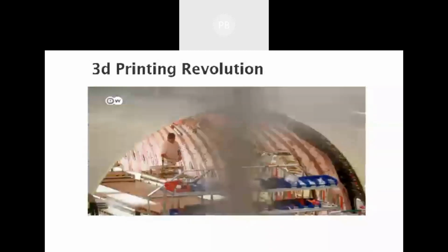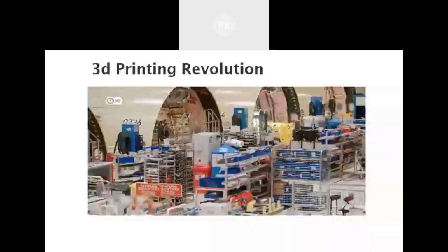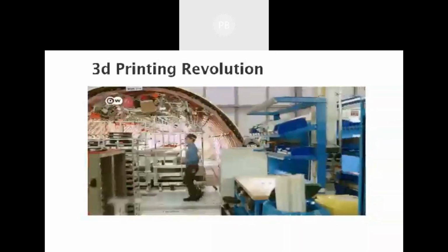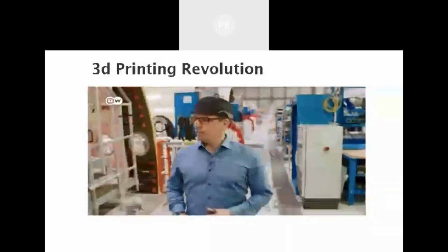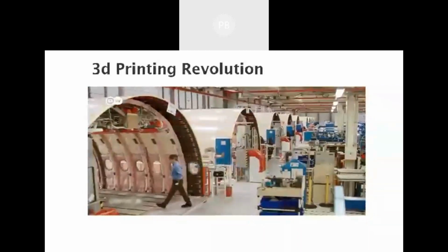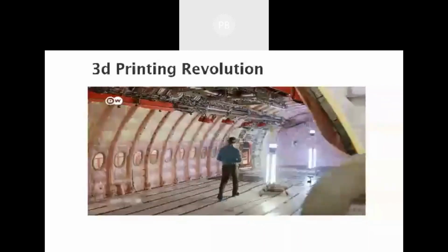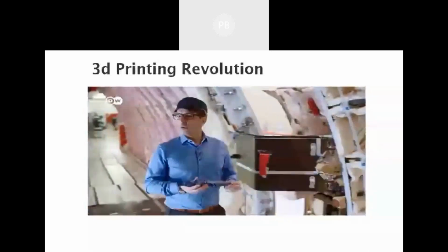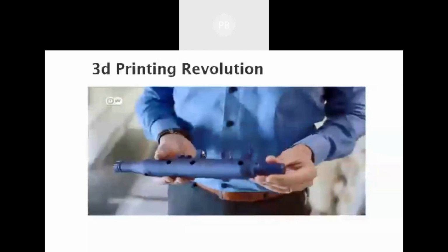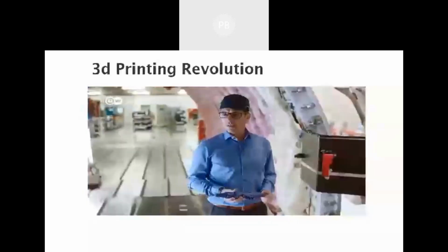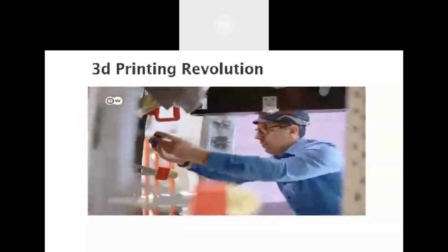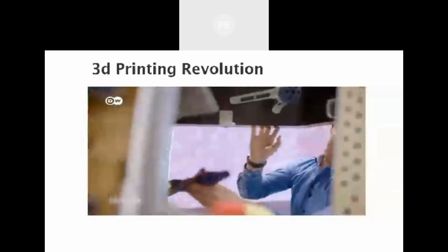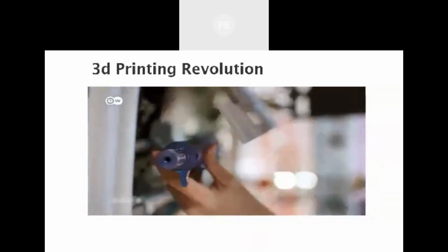This is where Airbus assembles its A350 passenger jets. A key component is now being printed in quantity, the door-locking shaft. They're due to fly in the aircraft later this year. This component usually consists of 10 parts, but the Airbus version has just one. We've integrated several functions and reduced the weight. There are 2 of these parts per door, and they make the aircraft lighter by 4 kilograms. That's a lot in the aviation world.